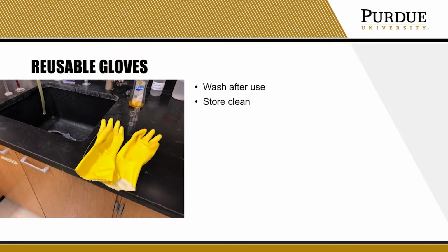However, there are reusable gloves. If you're working in a sodium hydroxide bath and you need some more sturdy gloves, put your disposable ones on, then put these reusable gloves on, say when you're washing equipment. At the end, wash your hands and wash the gloves. Wash the contaminants off and then hang them up to dry, and then those can be reused. You can tell the difference. These are a lot more sturdy, but after a while they're going to wear out too. So make sure there are no holes and those types of things. We see that a good bit.